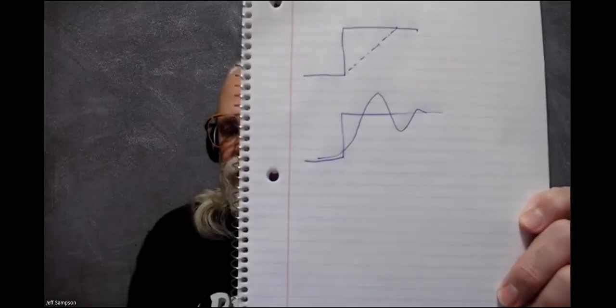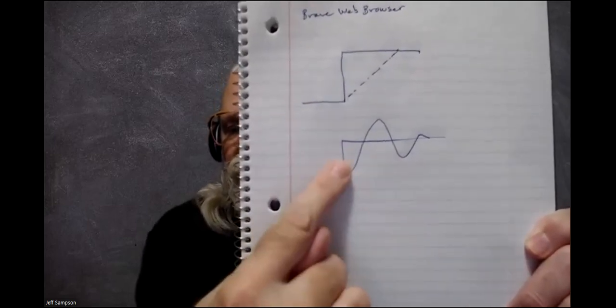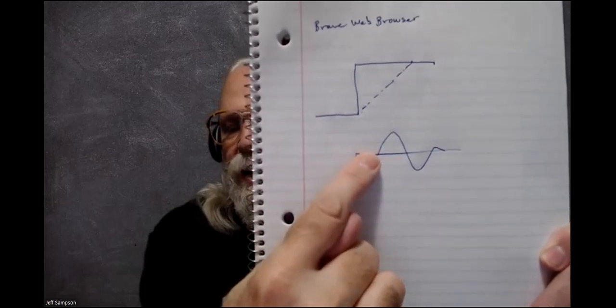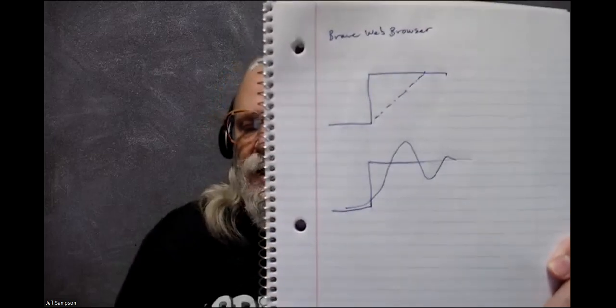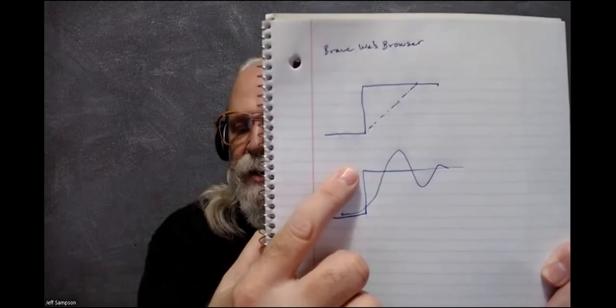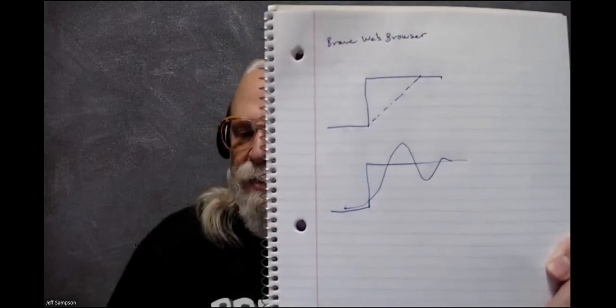So in this case, if you give it a step function, the motor is going to start ramping towards the destination, and the PID is going to let it go right past. It's going to oscillate. It's going to go past. So if that happens to be set at your hard stop, you're going to slam into the hard stop, and your motor is still going to be given full power to keep going, and you can't do that. It's going to break something.